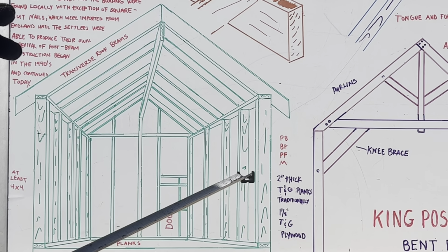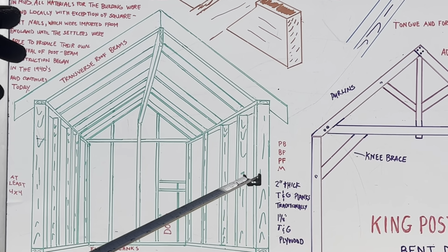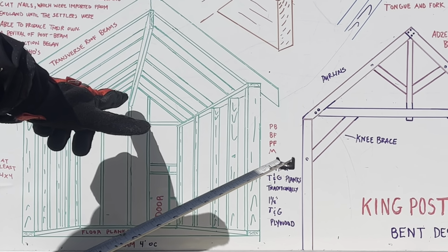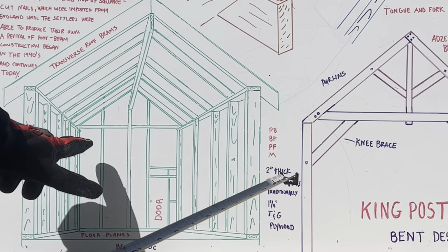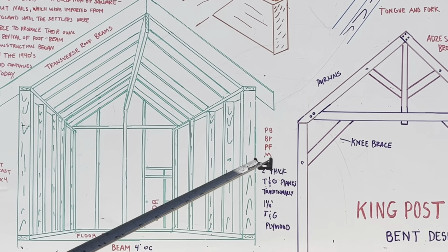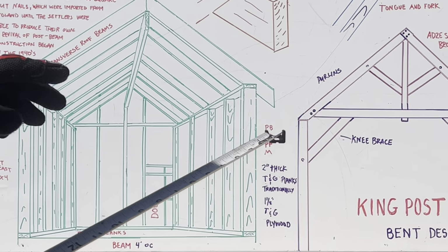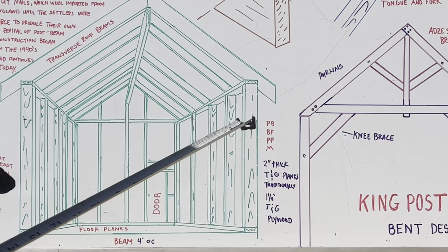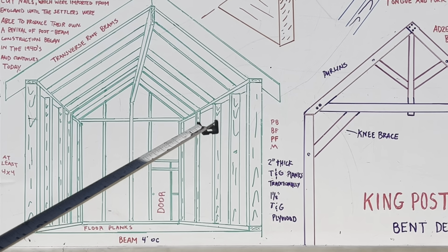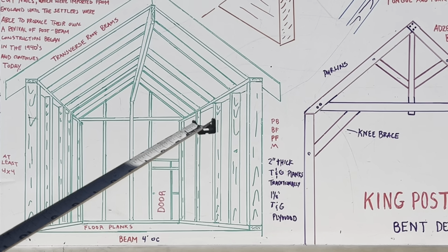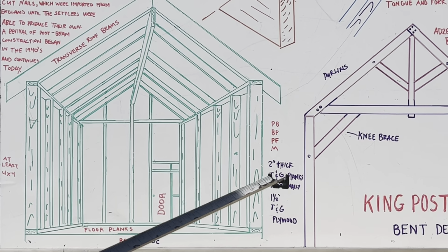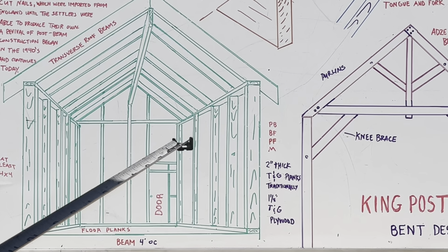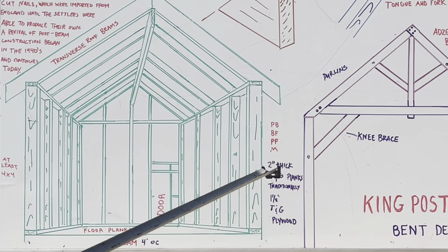Now, you can have several beams running like this beam right here, this middle beam, and you can have another beam right here on this post running the same way, and another beam right here running the same way, and take out your transverse roof beams and replace them with longitudinal. That's what it's called, longitudinal roof beams, okay? So you have more than this right here. You have one on this side, and however many else you need, and they'll be on top of your posts, okay?